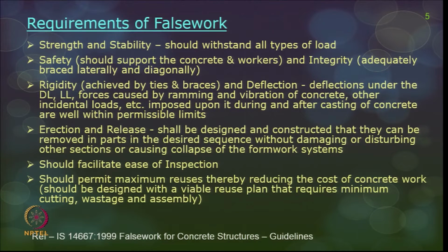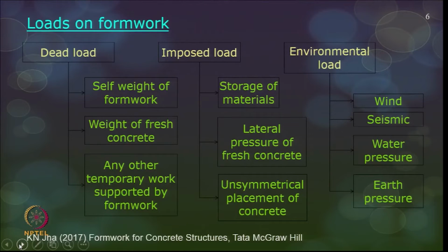Accordingly, the formwork structure and even the actual construction should be designed so that there is no complex or very particular shape wherein you waste a lot in cutting and reuse of the formwork. So, all these are the basic requirements for formwork.